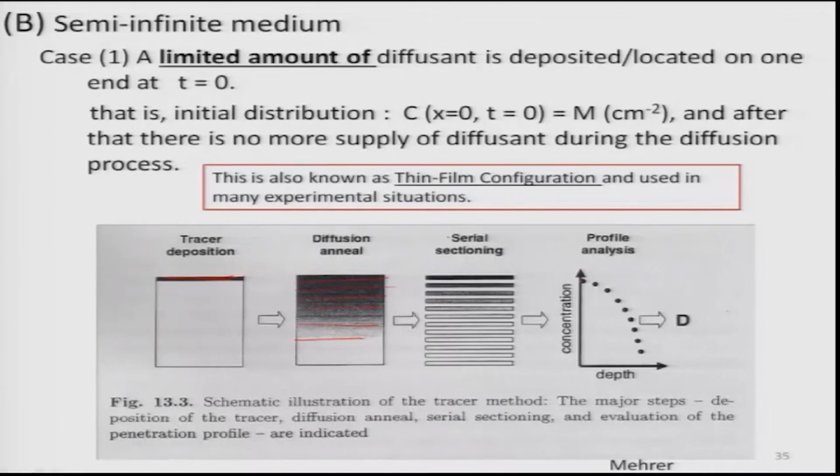Okay, so, in all this, remember one thing, we have assumed D is independent of time, sorry, of temperature, but D is never independent of temperature. When we are doing the diffusion annealing, we are assuming D is independent of temperature, but that is not the case, and temperature actually changes the diffusivity. So, how can we deal with that? Let us go back to our earlier lectures, on how diffusion happens in a substitutional solution.